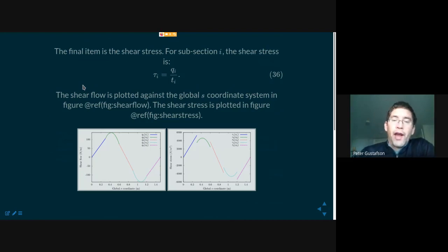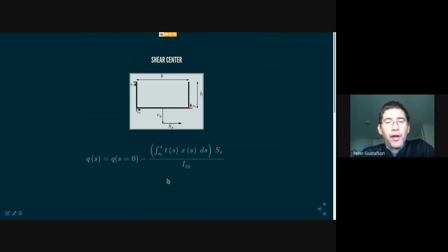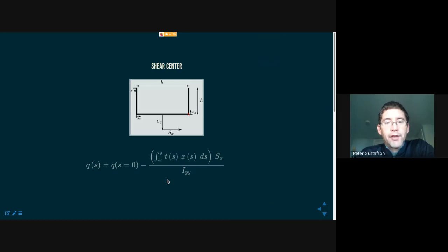And of course, after we recognized that the total shear on the entire cross-section had to integrate up from the shear flows, we were able to calculate the shear flows and their relationship to the shear load resultant. This is what it ended up looking like for a top hat style cross-section. Then I showed you this slide, and I said there's this concept called the shear center. And then I skipped ahead a few slides because we ran out of time.